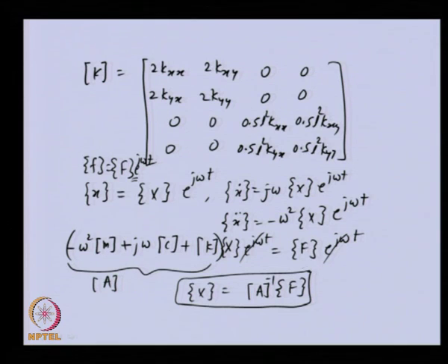We can solve this unbalance response X, which has 4 components in linear displacement and angular displacement in 2 directions. You can see here omega, the spin speed of the shaft, is variable. We can solve this response for various spin speeds, and plot how these vary with speed. Wherever the natural frequency coincides with this speed, resonance will take place. Those are the critical speeds.